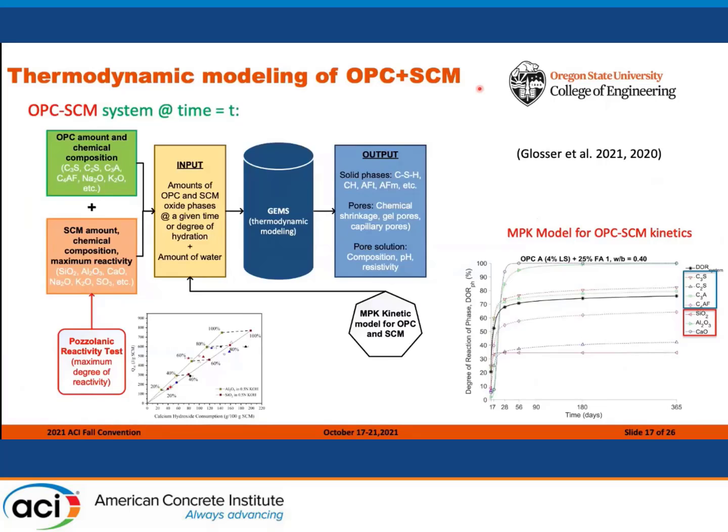Our work fills these gaps in the literature. First, we developed a Pozzolanic reactivity test to determine the maximum degree of reactivity of any SCM. Second, we extended the Parrot and Killoh model to cover the main oxide phases of a typical SCM. On the right, you see the modified Parrot and Killoh model, or the MPK model, that covers the clinker phases and SCM oxides.